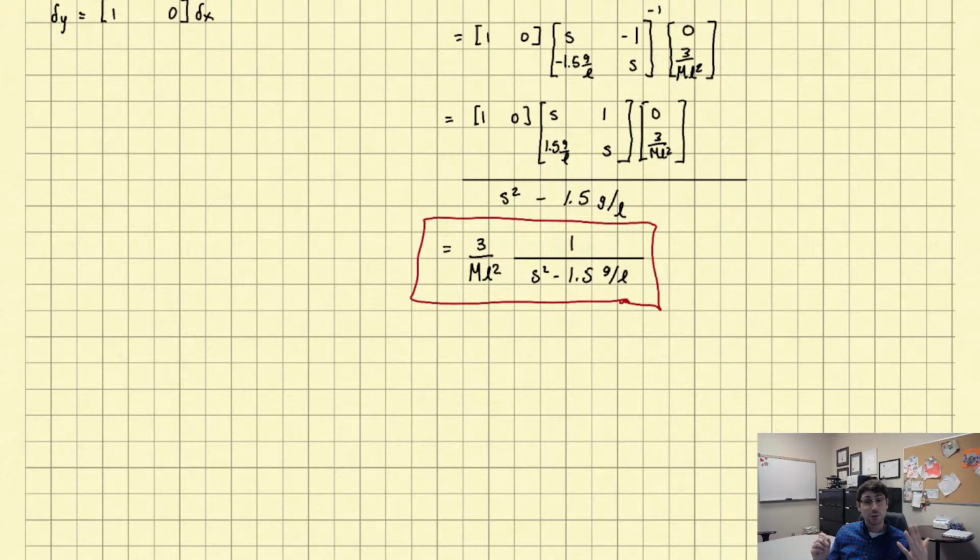Notice that, remember, this is the transfer function describing the linearization of the pendulum at its upright position. So notice, it's unstable. We have a pole with positive real part. Of course, this is what we would expect, right? We would expect that this pendulum is not stable upright. If we don't apply feedback or some sort of control, this pendulum will not stay upright. And of course, that's evidenced in the instability of its transfer function. On its own, it is not stable.